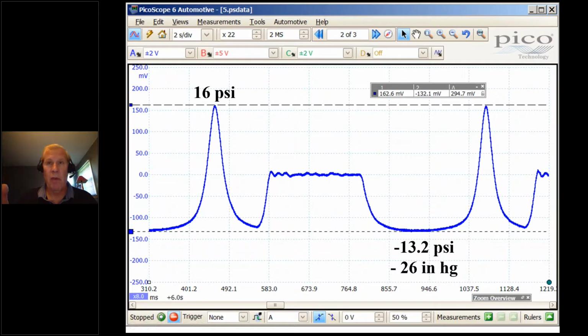So I know the exhaust valve opened. One could argue, if that's the exhaust valve opening, the exhaust valve was probably closed prior. So the exhaust valve was closed, and now it opens. And I believe it opens pretty well because we lose pressure and we come up to 0. And of course, an exhaust stroke, and this has no phasing, is normally 0 PSI, and this is right there. So I am determining that because I had an EVO, my exhaust valve was probably closed and it probably opened. And now I move to intake.